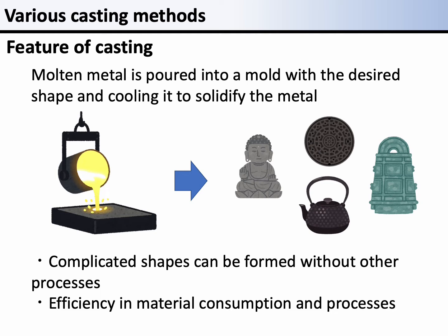Compared with making the whole shape of casting products by machining alone, the advantageous efficiency of casting is obvious. But the dimensional accuracy of the product is inferior to other processes. So, parts that require higher accuracy or lower surface roughness are finished by machining after casting.